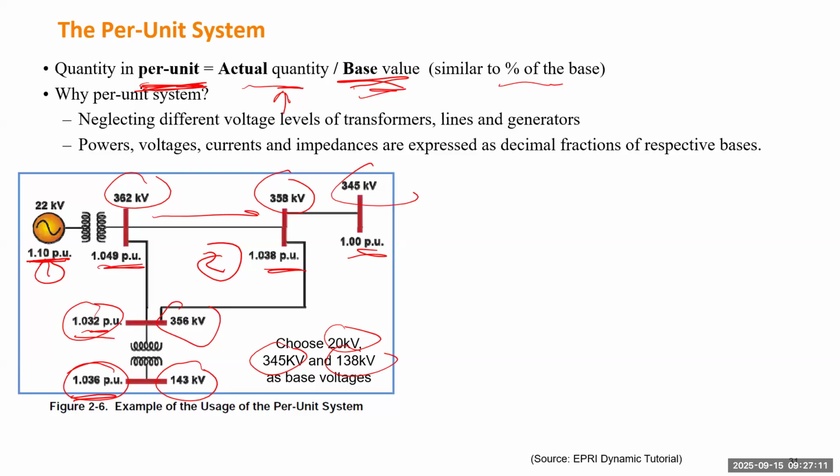So probably the bottom transformer, even a step-down transformer, which means it is sending power from a high voltage system to a low voltage system, but the receiving end may have some voltage control to slightly increase voltage relative to the base value. So this is a much clearer picture to see where you may have a high voltage problem or a low voltage problem.